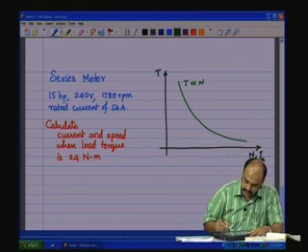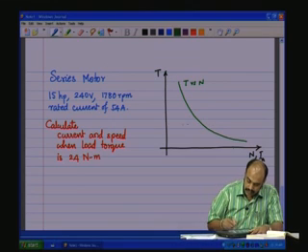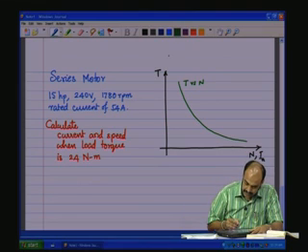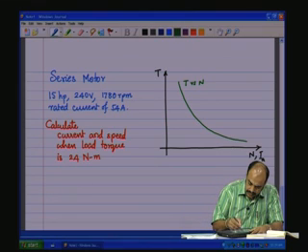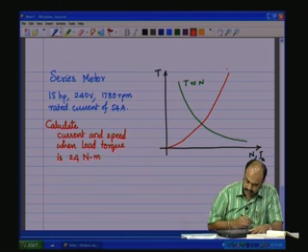As the speed is increasing, the torque is reducing, and at very low speeds the torque is going to be very high. Then there is torque versus IA. When IA is equal to 0 it is like that, and then it takes a square form because torque is proportional to IA square. So, it goes in this fashion.